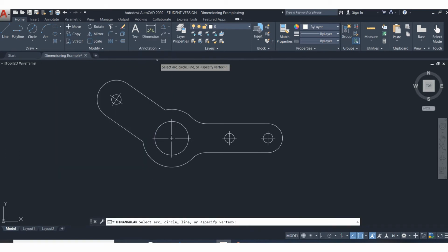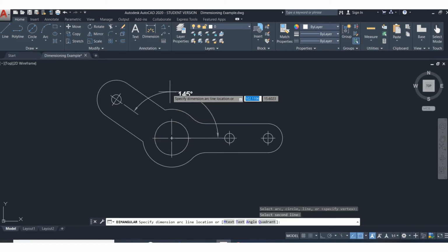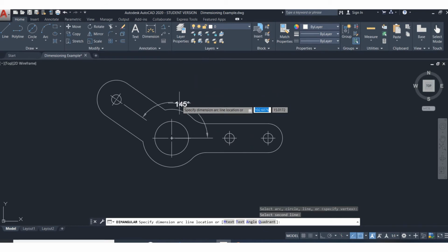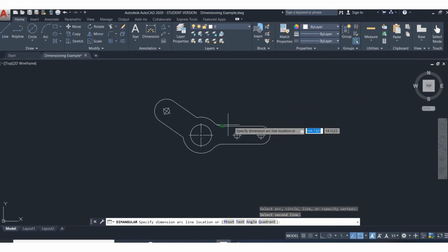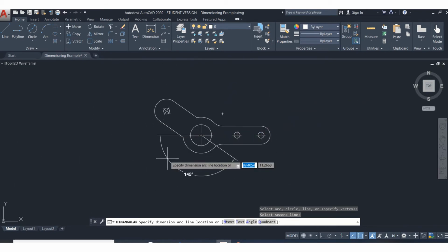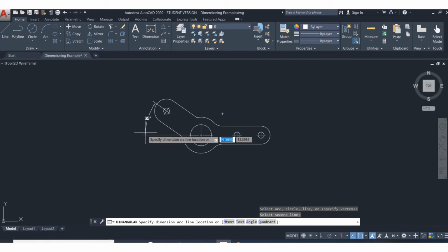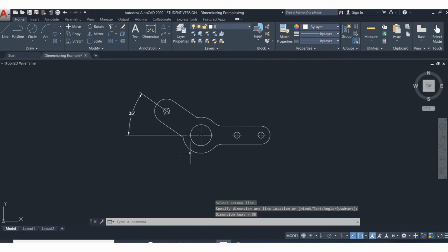For an angular dimension, you need to click on 2 lines that will represent the references for the angle. So for example, I need to call out this angle here. I can actually click on that center line, or center mark there, and you can see now I have to find a good place to put this. Remember, you cannot dimension on the part. You can have the arrowheads. Now there's lots of options here. I think you can move around and see what looks best. I think the best option is actually right there. It's really out of the way, and it's a good way to present that.